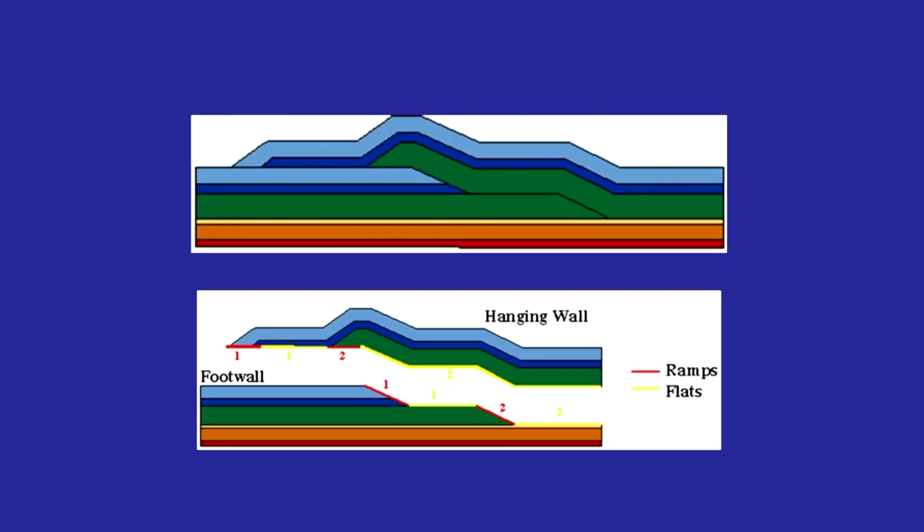So, as I have already presented this, but a few slides we will repeat so that we have the continuity. Before going for trenching, we also usually go for geophysical mapping. What we see right now is the GPR profile, which was collected across the scarp, which clearly indicates the faults over here. So, that also helped us in identifying the near surface deformation.